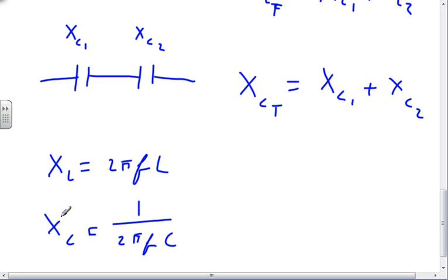So when I change it to X of C, I'm in ohms. So I treat the X of C value just as I treat ohms that are real, from a resistor. I'm going to have an imaginary number and go negative on me. That's a different issue. But when I do the calculation, I can just add them.